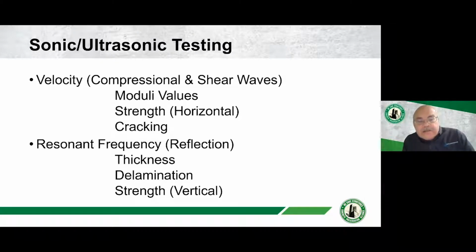The velocity, there's different types of energy waves. There's a compressional wave, there's a shear wave. They travel at different speeds and have a different fingerprint or a different signature, if you will. But as we record these velocity measurements, it's very easy to calculate the moduli value.